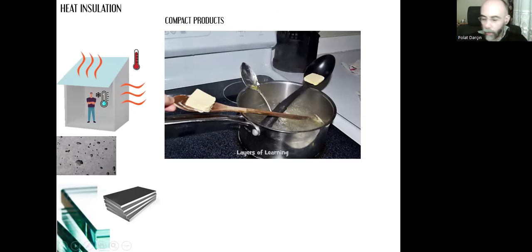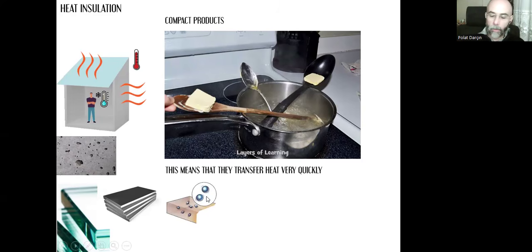The butter in the metal spoon has already melted because the metal doesn't have any pores. It's a non-porous, very compact substance. It transfers the heat so quickly. That's why the butter is already melted. In the opposite part, we have timber, which has lots of voids, channels. That helps with decreasing the heat transfer speed. We cannot stop the heat transfer altogether. We can slow it down because the gaps will help to decrease the speed.